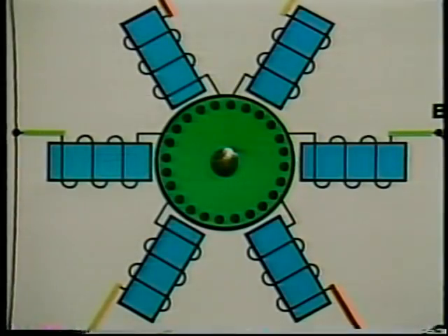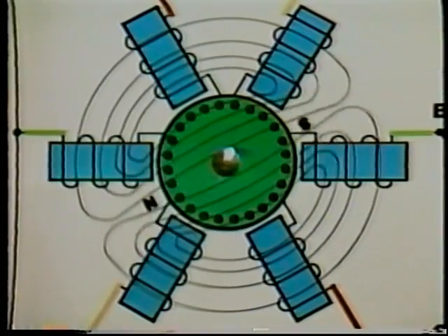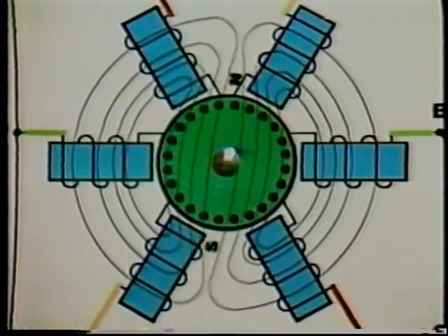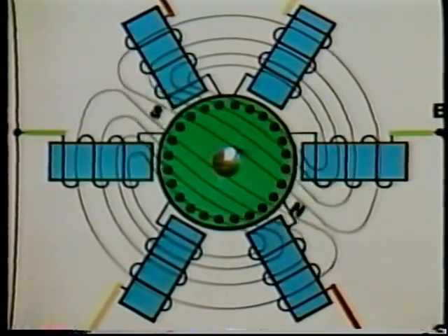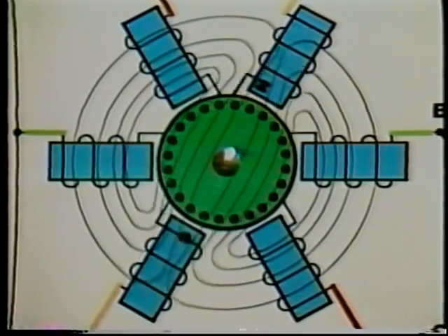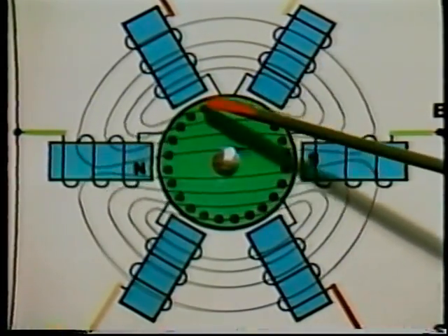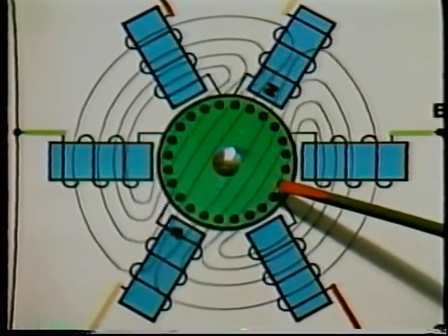At startup, as soon as alternating current is switched on to the stator windings, magnetic poles travel around the rotor at synchronous speed. The rotating flux lines sweep past the stationary rotor conductor bars rapidly and induce maximum voltage in them.